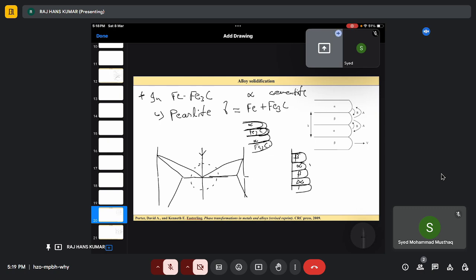Again there is a formation of beta. Again, they will grow. They not only reject this side, but also grow in this direction. Because of this alpha rejection, whatever atoms the alpha rejects, they will go because of the concentration gradient. They will move here because beta needs more solute. So beta takes up solute atoms, and because of this concentration gradient this interface will move.